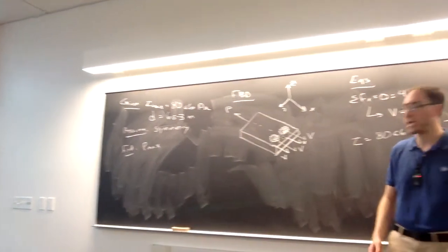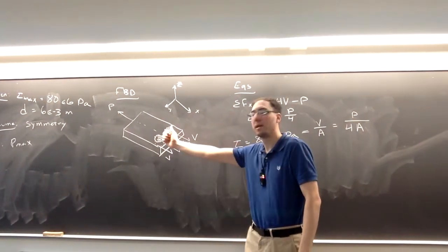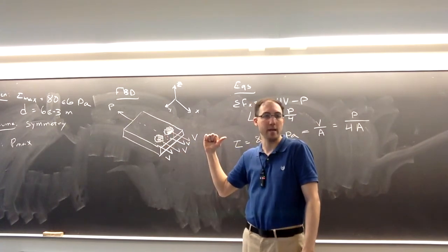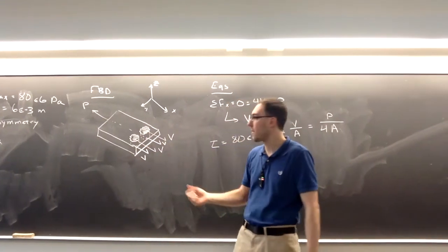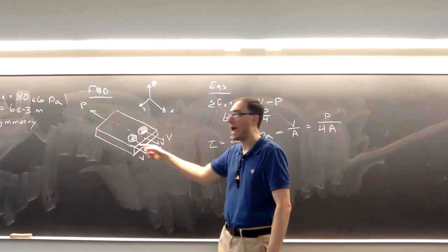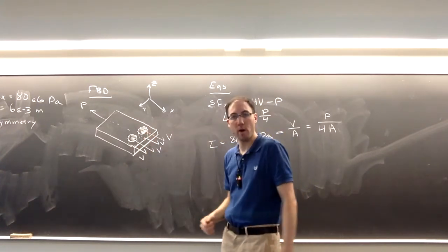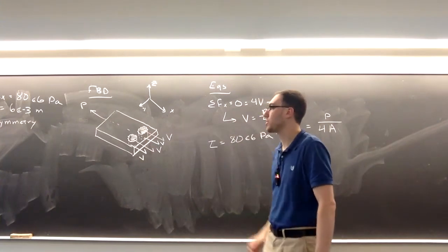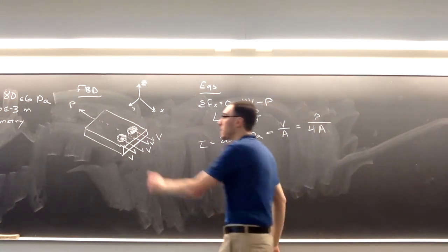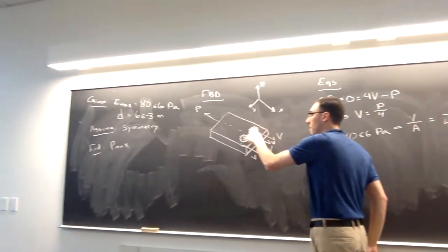Another way I could have represented this is to make all 4 of those cuts and say there's one collective V acting on it, but then the surface area will be all 4 added together. In this case, the V is only acting on the surface area from one bolt, which is just this single surface area here.